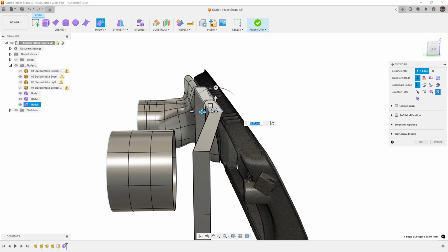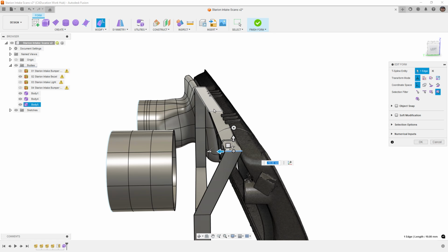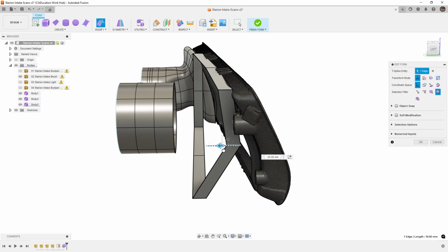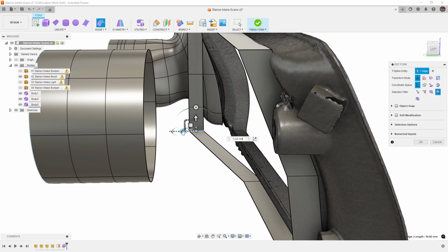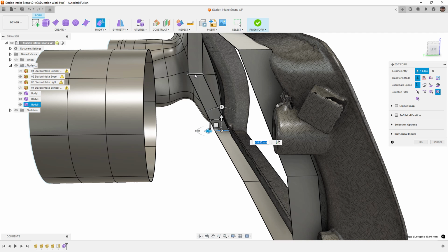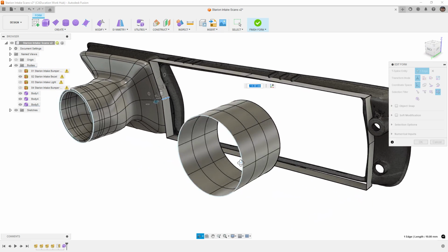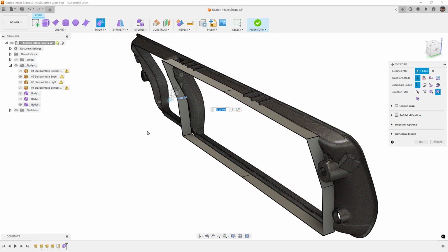We do have a couple of structural ribs up there. Not too concerned with it at the moment, but I am going to have to make adjustments to the shape in a bit to account for that kind of stuff. But right now I'm just trying to get it roughly close to the shape of the bezel. And then we can do some fine adjustments. This is a similar workflow if we're working with surfaces. You start with big, broad surfaces, the main ones that are going to drive the curvature, and then you kind of work backwards from there.